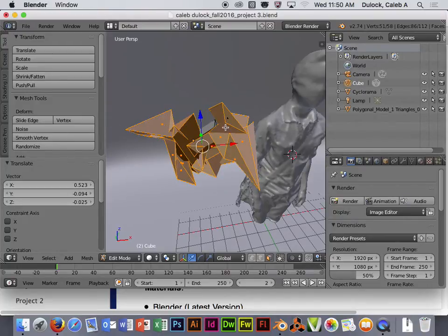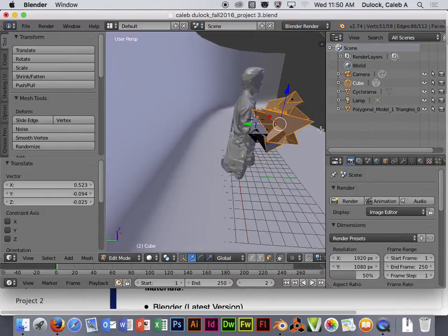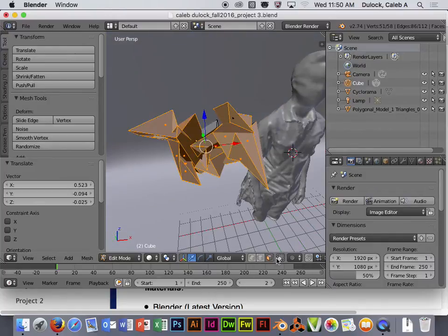If you ever want it to be able to select all the way through the object, instead of just selecting polygons from the side you can see your object on, there's an icon down below on your 3D menu bar, right next to the three little cube icons. And it looks like two little overlapping flat squares that have little white circles on each corner.